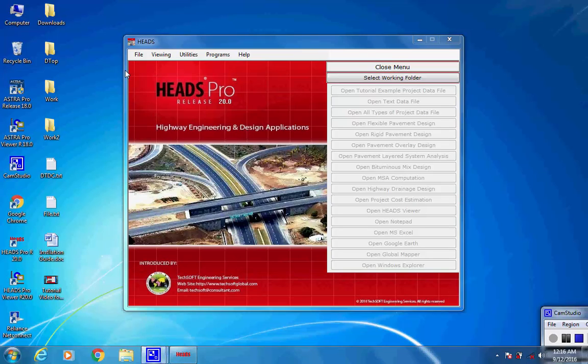In this session we shall see the various steps involved in the design of grade-separated interchange at a highway crossroad. The design involves two intersecting main highways. One highway is elevated at the intersection with either end at grade, and another highway throughout at grade, and we need to design 4 loops connecting the at-grade with elevated highways and 4 slip roads connecting the adjacent sides of the 2 highways at the ground levels.